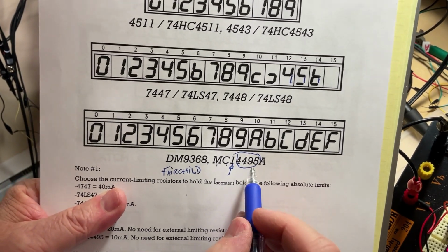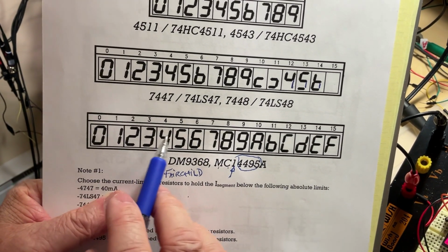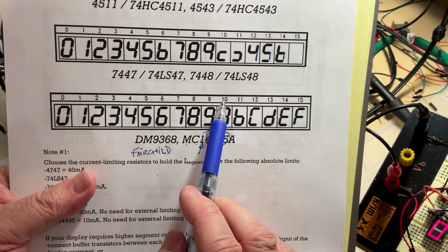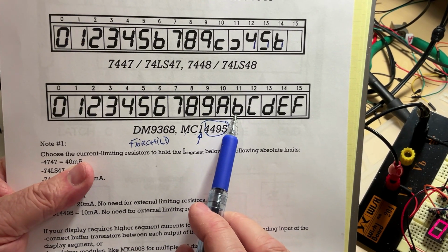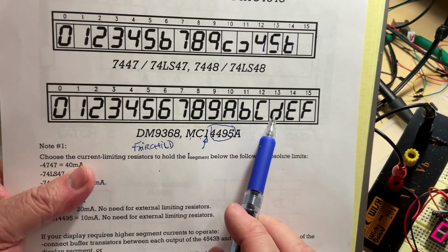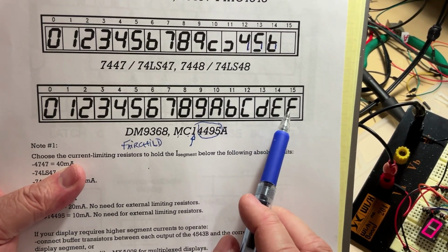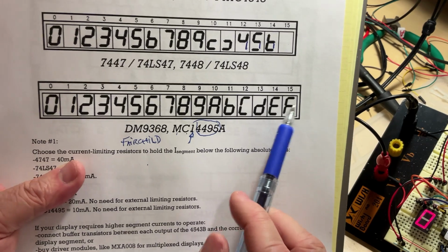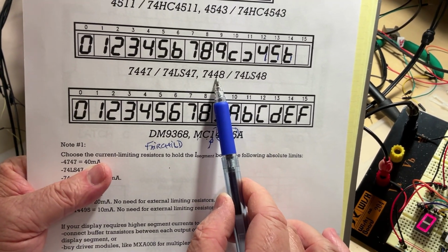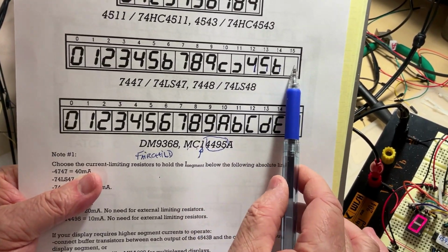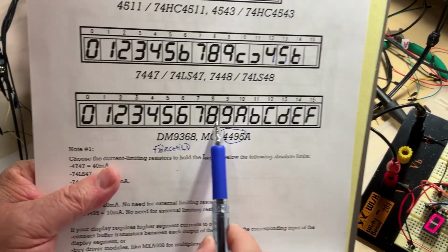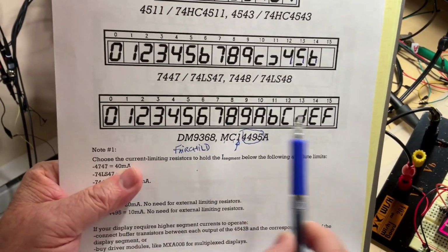And if it is the case, on the 7-segment display, this is what is going to show. It shows the letter A for 10. It shows the lowercase b for 11, uppercase C for 12, lowercase d, E and F for 13, 14 and 15. So you see, this particular decoder does a different job than the 7448, because starting from 10 to 15, they don't show the same thing. So that one is able to display up to 15.